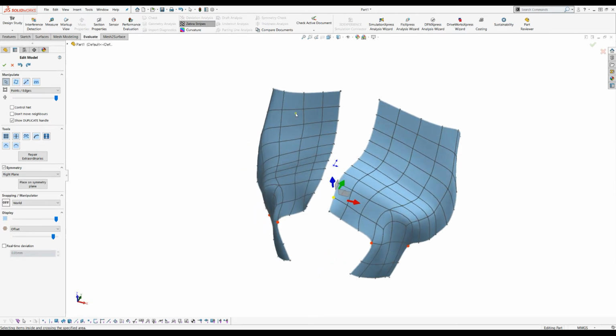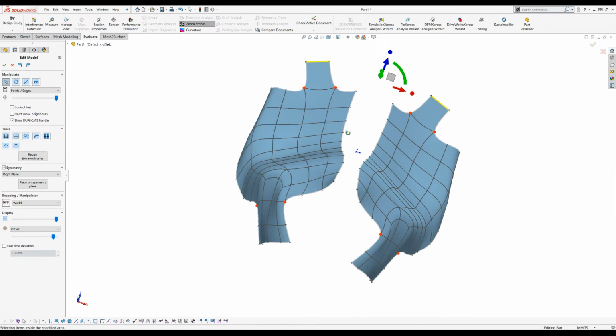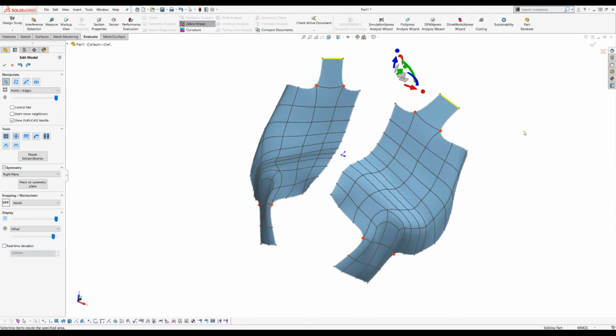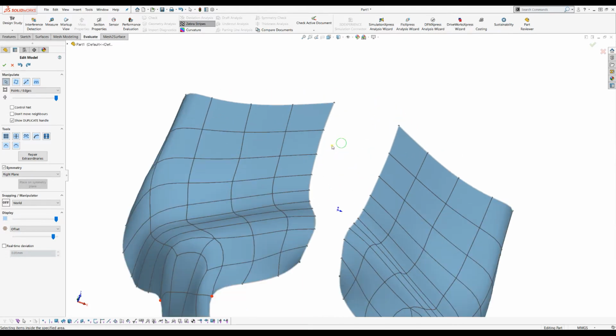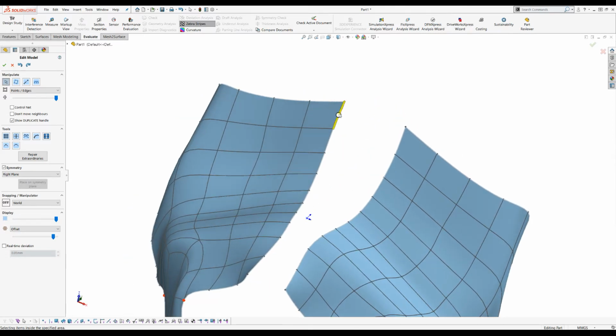This is my part that is symmetrical. What it means now is that if I just take a point, because it's symmetrical, you can see that it's mirrored and you get the result on the other side. I will Control Z. The problem now for me is that I want to actually join these two and put them together, but they will not merge even if you see this sign, because this part is a mirrored object of my original one.